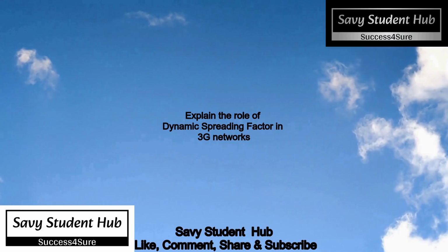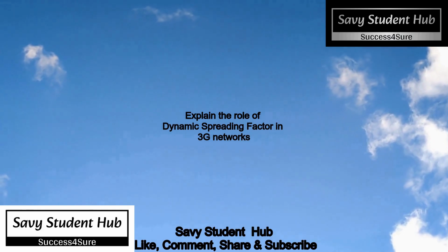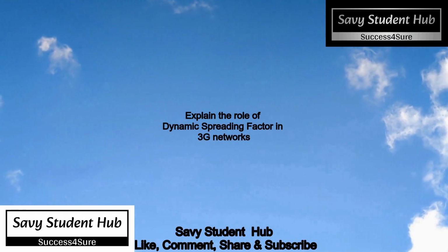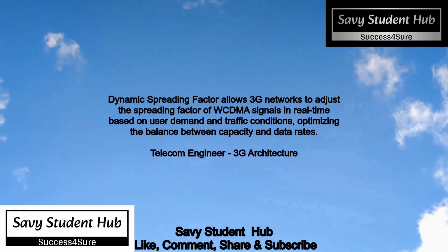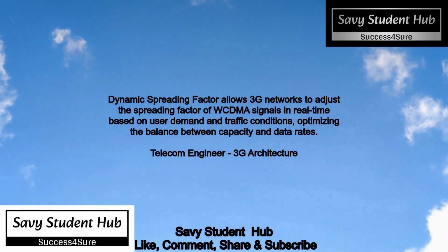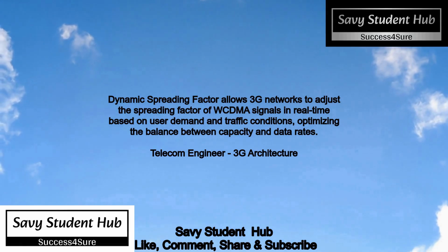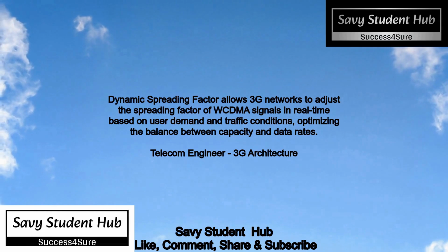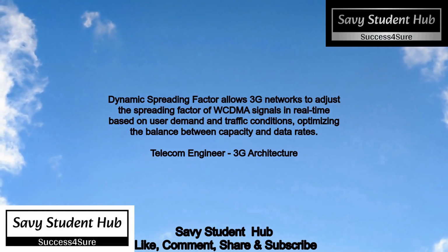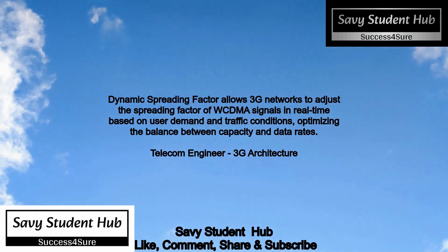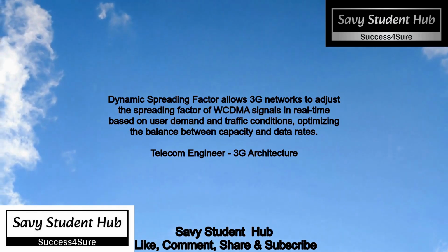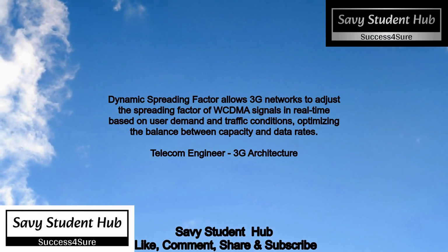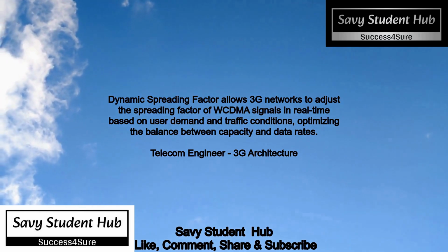Explain the role of dynamic spreading factor in 3G networks. Dynamic spreading factor allows 3G networks to adjust the spreading factor of WCDMA signals in real time based on user demand and traffic conditions, optimizing the balance between capacity and data rates.